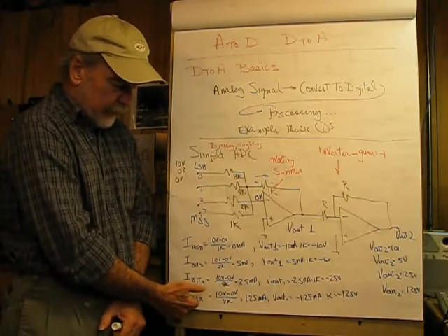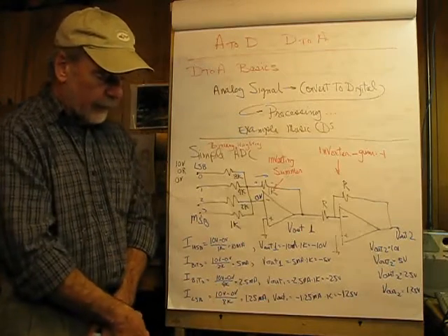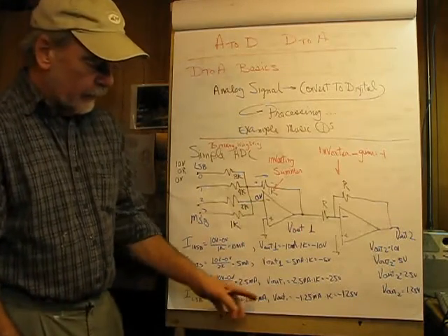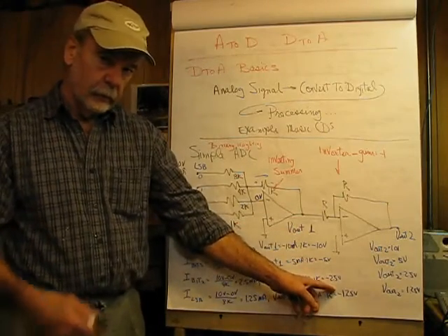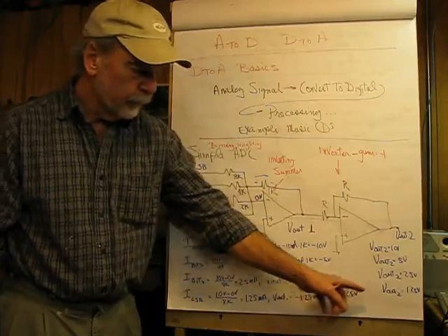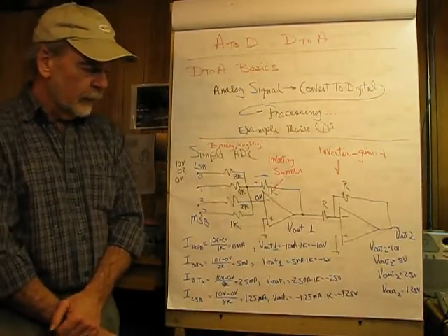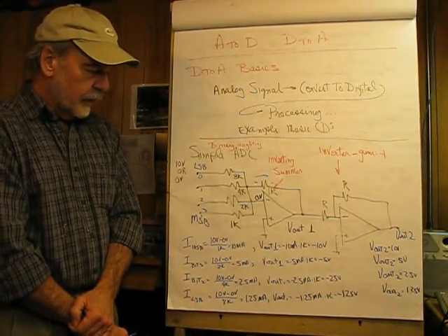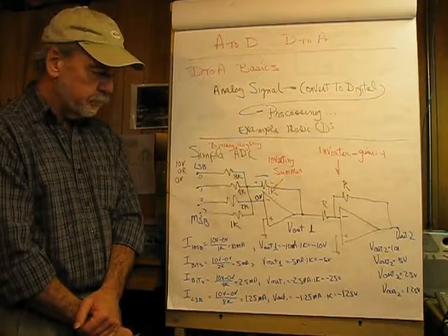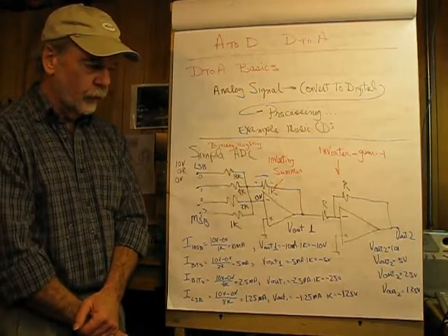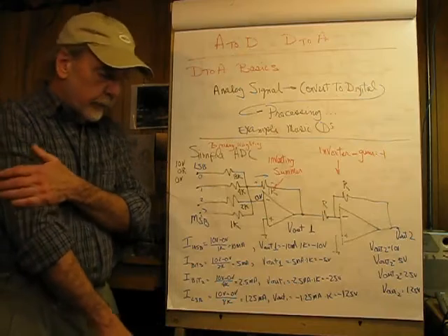So that for the LSB, least significant bit, will be 10 volts minus 0 divided by 8K. And then the contribution of that at this point would be a negative 1.25 volts. Then inverted would be plus 1.25 volts. So what we can see here is that we can effectively take binary weighting and produce outputs which correspond to the weight of the actual binary input.